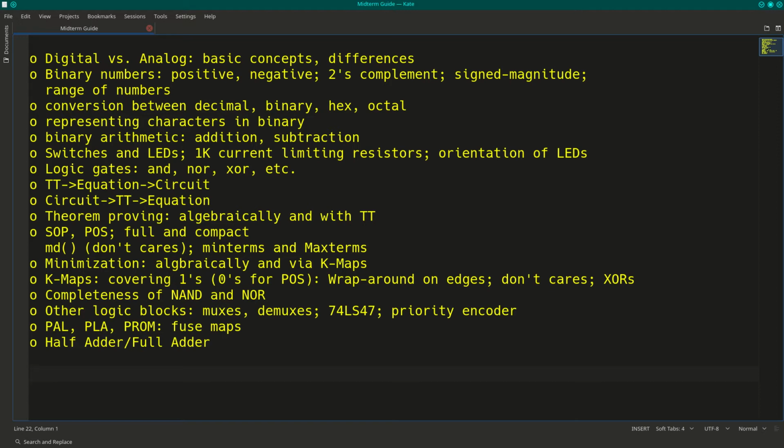Switches and LEDs, so still a perfect record on labs of switches hooked up correctly. So that's good. So you'll be wiring up some switches and LEDs. Make sure you use a 1K ohm in series with LEDs so you don't burn them out. LEDs are oriented.